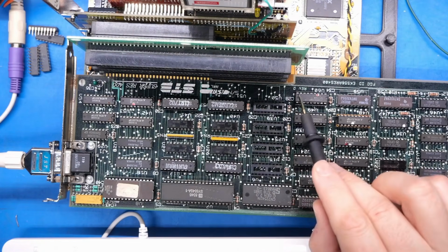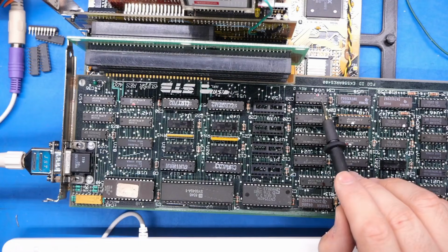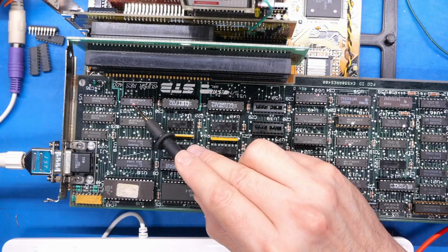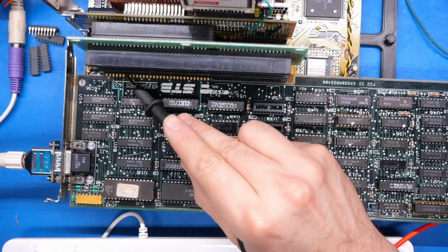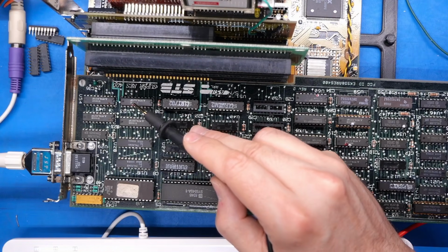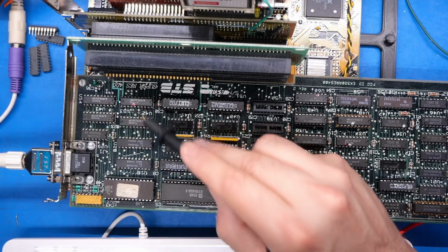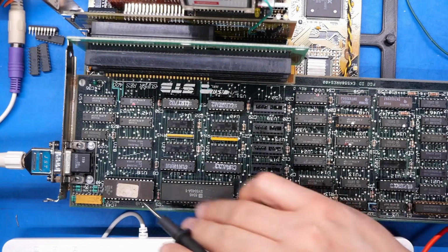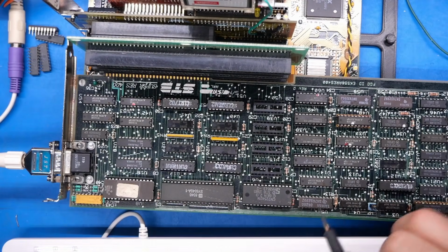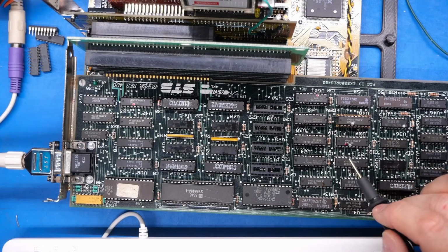And the reason why is the other connection. This red mark here goes to the RAM chip. It also goes over here to this chip, and this right here is an output. And the input of this chip goes to the ISA bus on one of the pins here. And that's obviously one of the ways that information is sent from the computer into the DRAM. But I think this part over here has to do with the ISA bus communication and is not what we need to focus on. I think what we're dealing with is something over here.